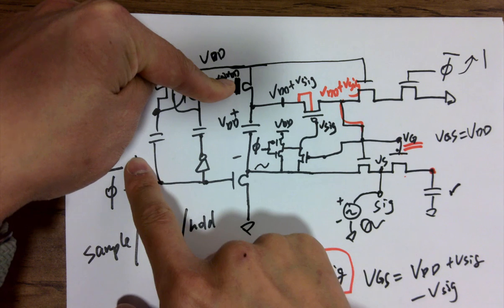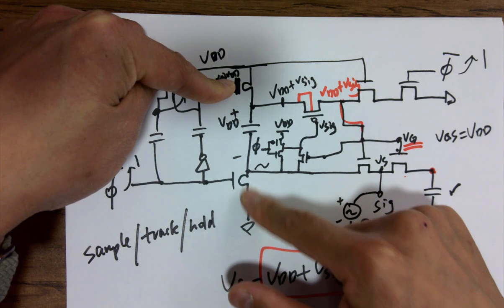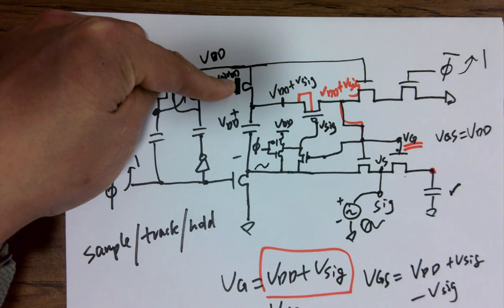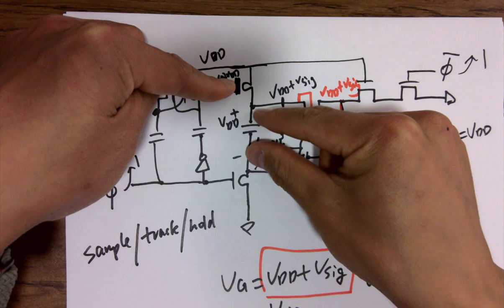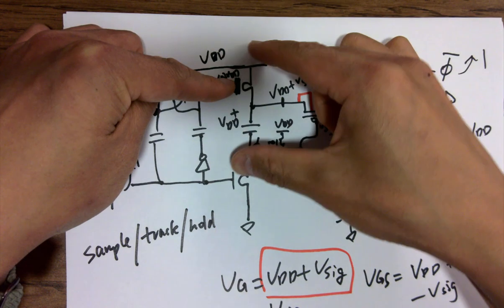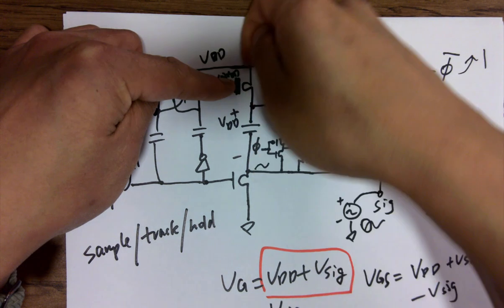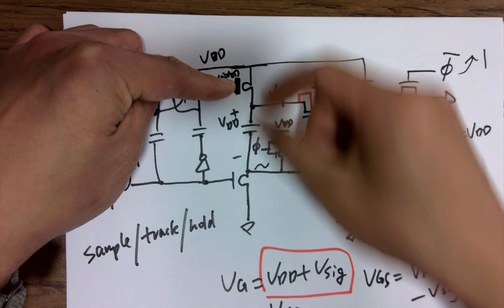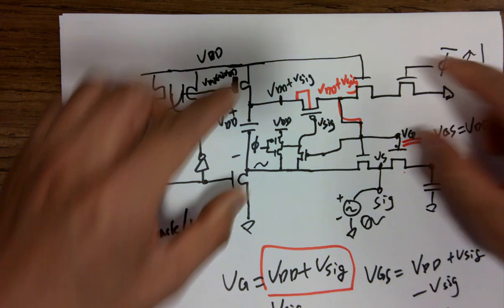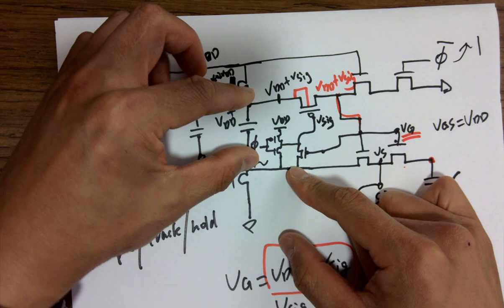This is a rising edge, so this NMOS is on. You get a channel. It starts doing what? Discharging to the ground. It's like a waterfall, right? Boom, go to the cap. This is wide open. You can just dump the entire VDD to this capacitor. Just keep dumping, right? Okay, charging up. It's waiting for this one to go to 0 again, and it stores the floating VDD. But before that, it's charging up.